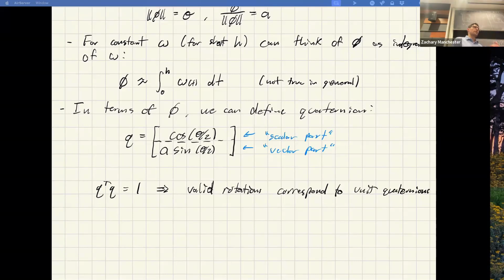And a fun fact here is that rotation matrices, if I do numerical integration and I get drift where it's not quite SO3, not quite orthogonal, whatever, those are a pain to normalize back to a rotation matrix. You can do it. Anyone know how you do it? Fun fact. How many guesses? Turns out you have to SVD it. So if you SVD it, you get a rotation matrix times a diagonal matrix times a rotation matrix. You take the SVD and then you set all the singular values to 1 and smush it back together. So that's how you do it for a rotation matrix, which is a pain. For a quaternion, you just have to normalize it, which is super easy. So much, much easier to normalize.